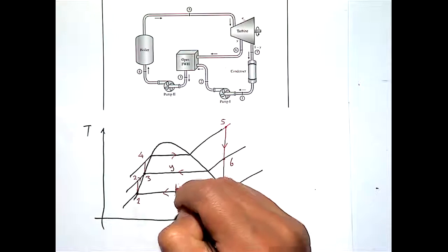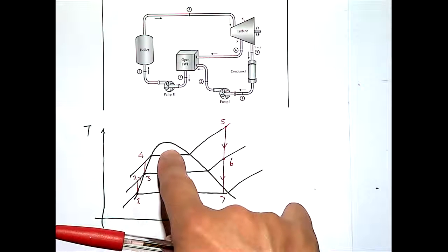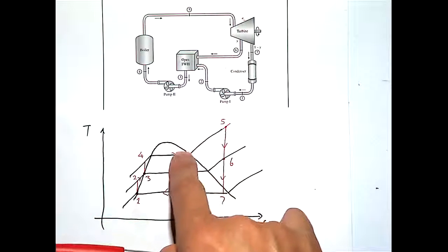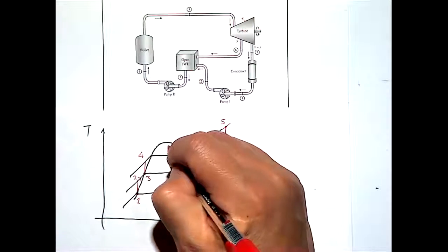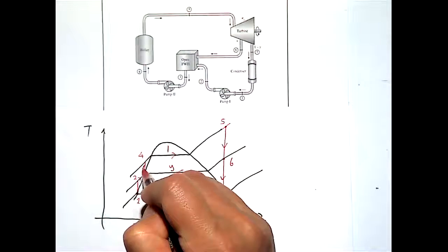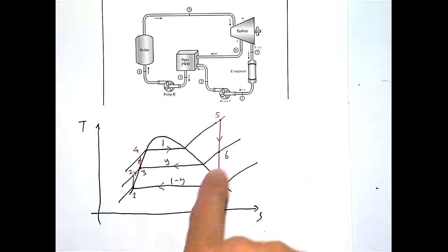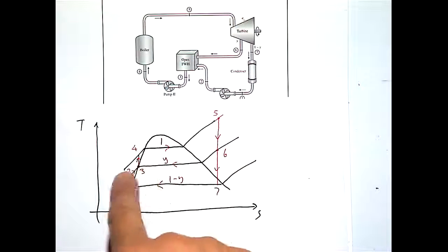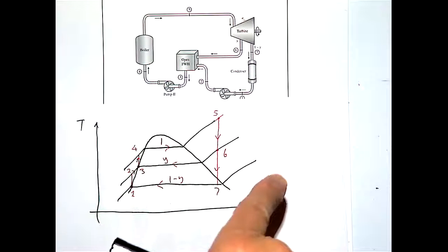And this line, y or 1. This is where the two streams join together, and then go through the boiler. Right. So in terms of calculation, you need to pay attention that each energy term, heat or work term, has a mass fraction attached to it.